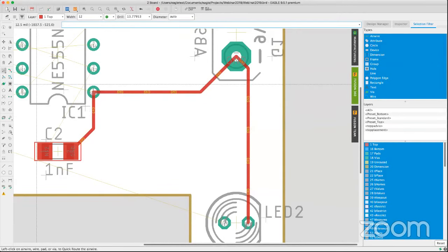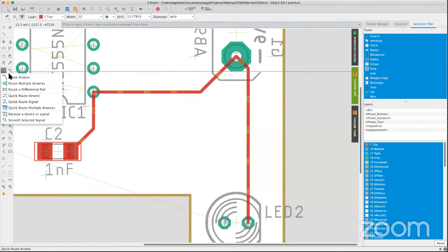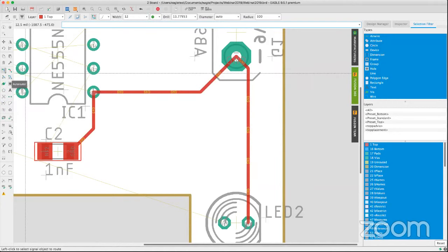Okay, I'll go back to our regular manual routing AirWire format, and you're going to notice that there are 3 modes that I could use, up on top on the parameter toolbar, this bar right here. You'll see that I could push obstacles or I could go full manual.